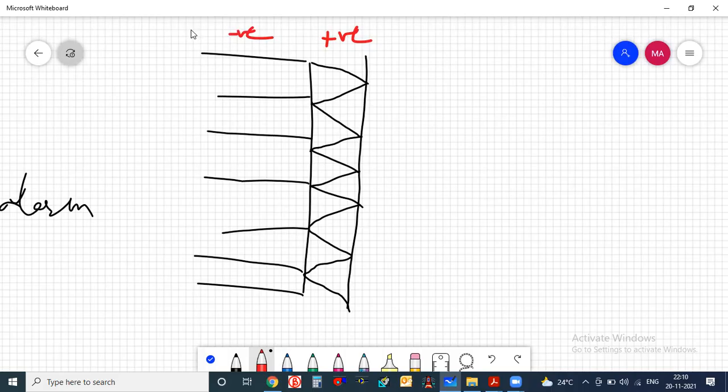The meaning of negative and positive pressure is that everywhere you will see one door will be there. What is the meaning of positive pressure, in simple definition: if this door is closed, air cannot travel from this point to this point. This is the positive pressure. But air can travel back from this point to this point, because I have maintained the positive pressure.